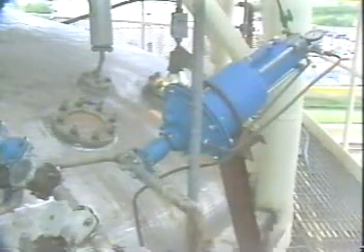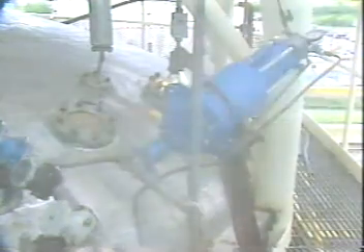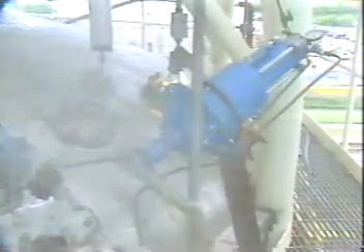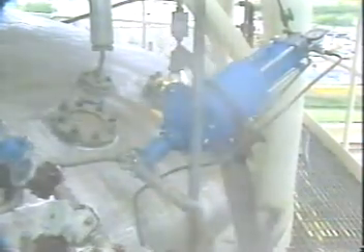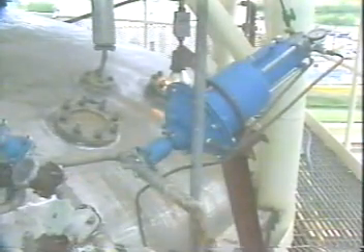Another electrical hazard is static electricity. In some applications, it's necessary to install a control valve such that it discharges directly into the vapor space of a tank or vessel. When this occurs, it's possible for the high-velocity jet stream exiting the valve to create a high static charge on the tank nozzle. If the vapor consists of a flammable mixture, a hazardous situation exists. So it's necessary to provide a means of eliminating any accumulation of static charge.